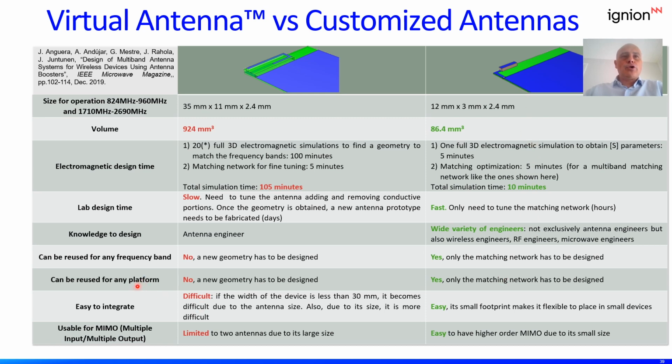About the reuse of these self-resonant antennas for other platforms on other frequencies, it's difficult because once the antenna is resonating at some particular frequency, it's difficult to have performance at other frequencies. However, with virtual antenna, since this is a non-resonant element, you can add a matching network to tune the frequency